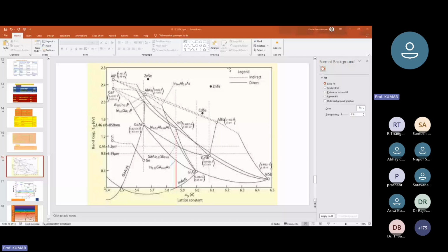Let us say gallium arsenide, it can produce RF amplifier and microwave devices. Gallium nitride is a wide bandgap semiconductor with a high breakdown voltage and relatively high mobility. So it can be used in power electronics, it can be used as LEDs, and also in RF applications. As I told, it can be used for high frequency and high temperature operations. Silicon carbide is another powerful material used in power electronics, particularly in e-vehicles nowadays.